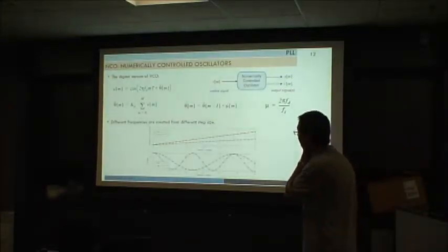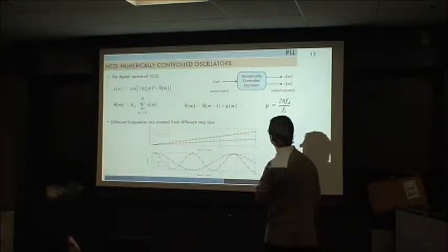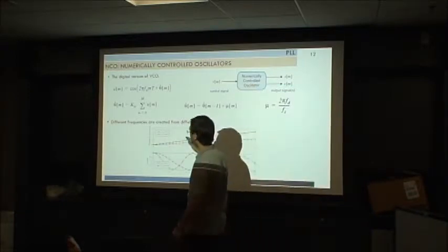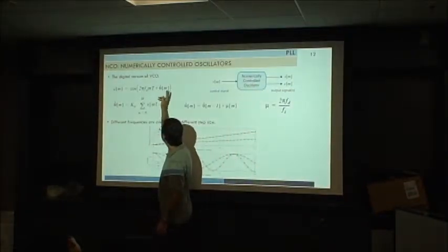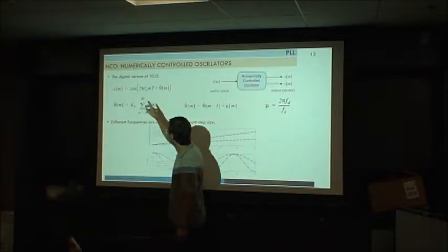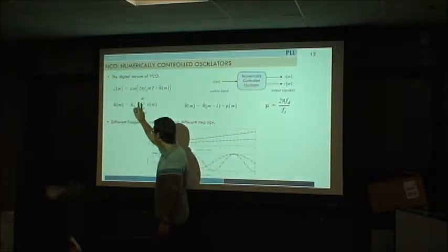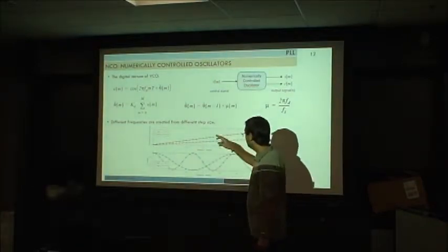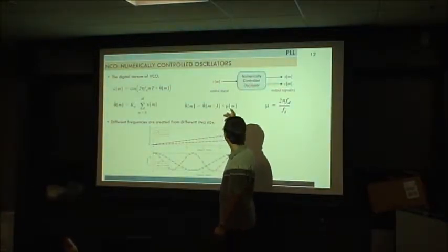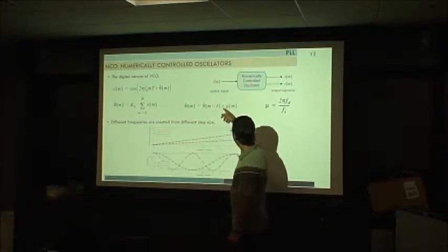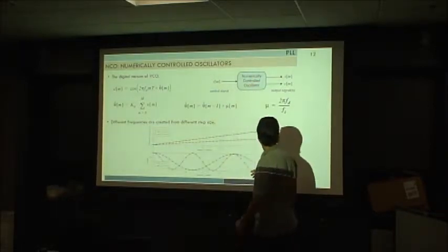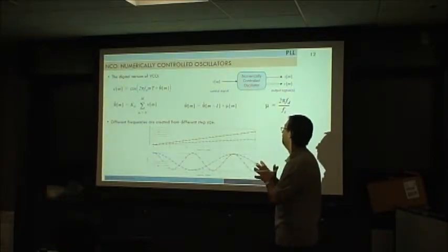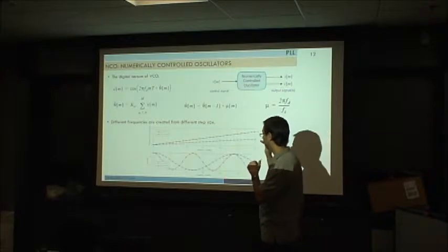Well, but really, what we will use is this guy, the numerical control oscillator, which is just the digital expression. You can see we replace t, continuous time, by discrete time, the integral by this summation, and the estimation will be the previous one plus some factor here, and we will see how that factor affects things. In the design, you should be careful about that factor, which is just a step.